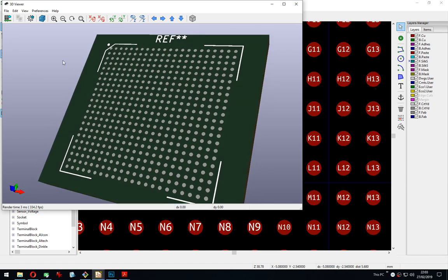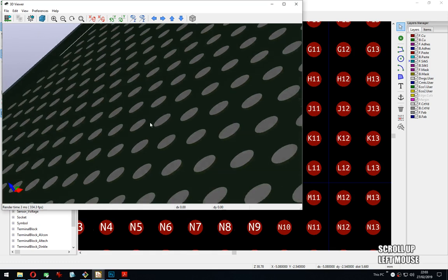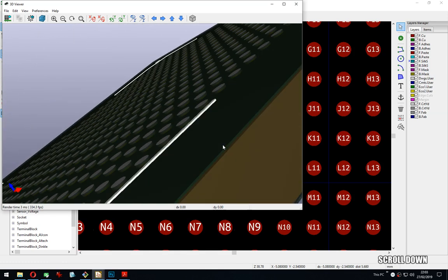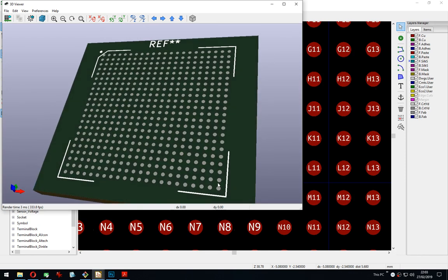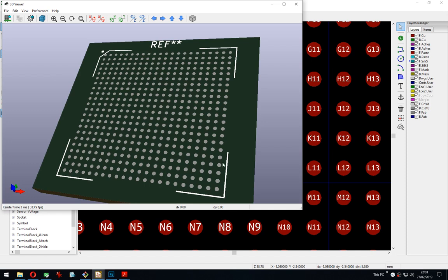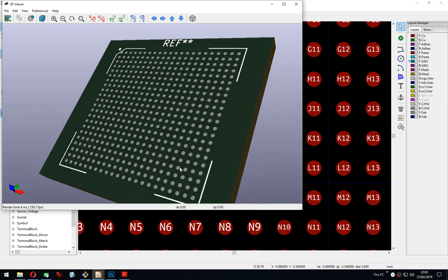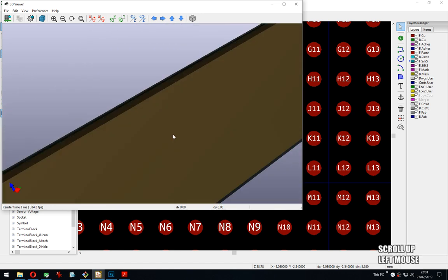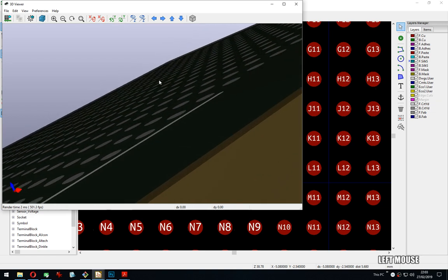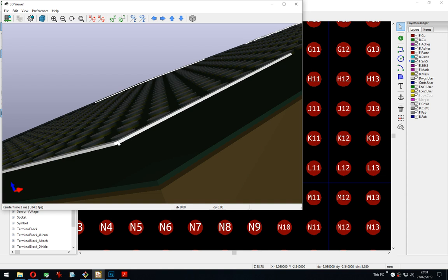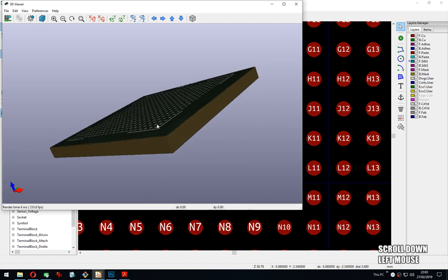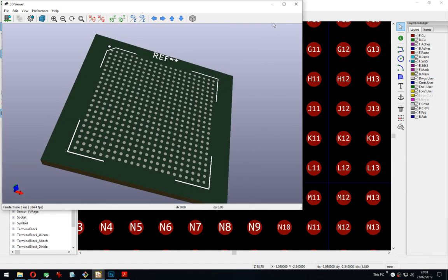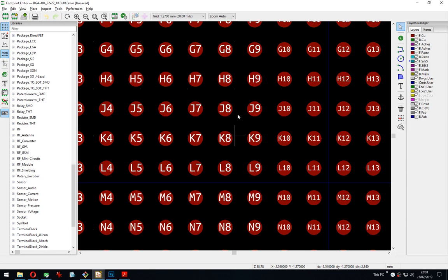And there it is. That looks good. There's solder paste on it. And some people don't use solder paste for BGAs because, I mean, BGAs have balls of solder, so why would you do that? So that's something I should think about, because for the previous board I did use solder paste and there was no problem there. So if it works, maybe don't change it. I really like that. Even the silk screen has thickness. They really made it nice. Yeah, the 3D viewer is pretty cool.